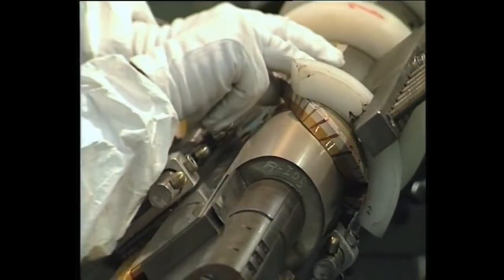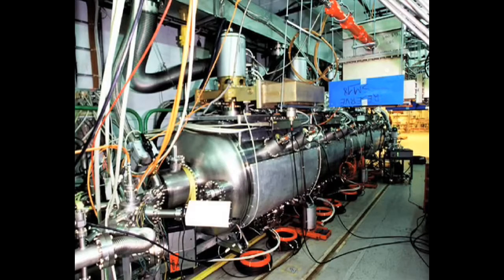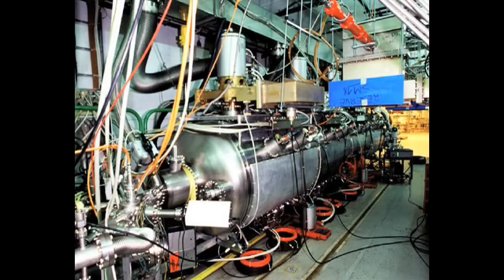So it took about 3 years only to make all these steps into a successful dummy coil, successful in the engineering sense, not in the performance sense of the coils. We had only one chance to build it and to test it, so we had to incorporate a lot of diagnostics: many voltage taps, thermometers, strain gauges and things like that. For the CERN people that was a naughty surprise, because we came to the test station at CERN with a magnet with about 300 wires coming out of it, and they expected only about 12. So it was also a new exercise for the station at CERN to test this magnet.